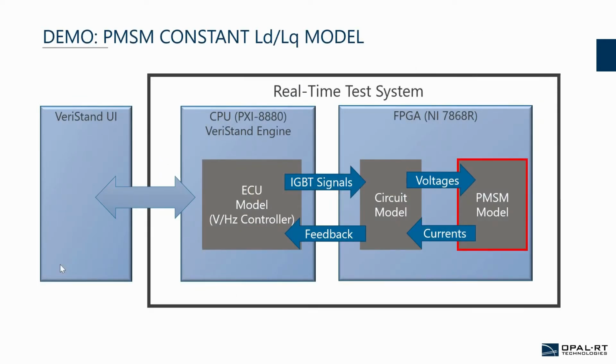I've prepared two demos for today. They are both similar and simple, but they should give you a good idea of the workflow. The first demo is an example of controlling a machine using a software model executing on the CPU. The software model is specifically an implementation of a volts per hertz controller. Since the machine is not being controlled by an external piece of hardware like an ECU, but instead by the simulated controller on the CPU, this would be more accurately described as a model-in-the-loop type demo.